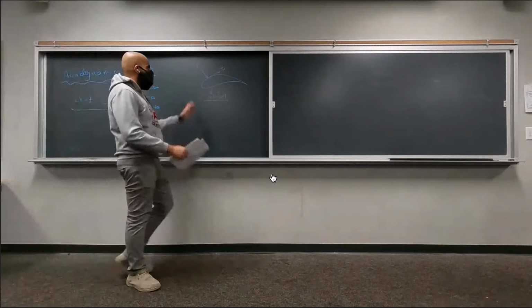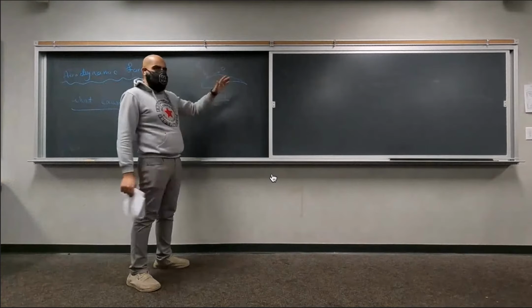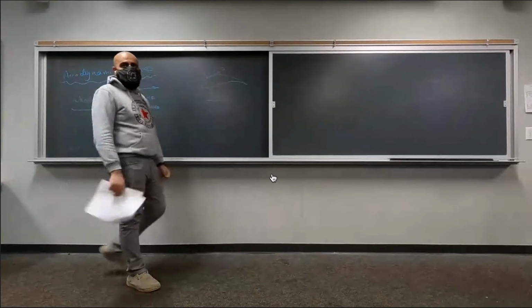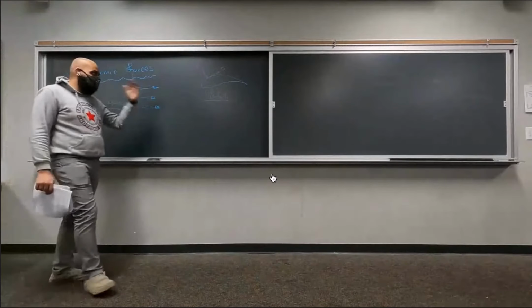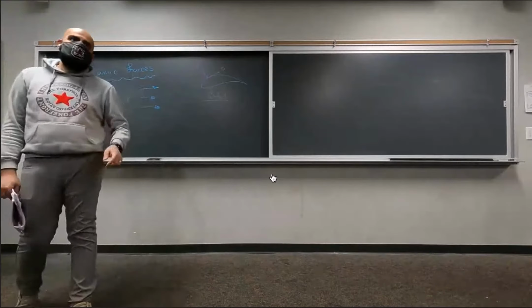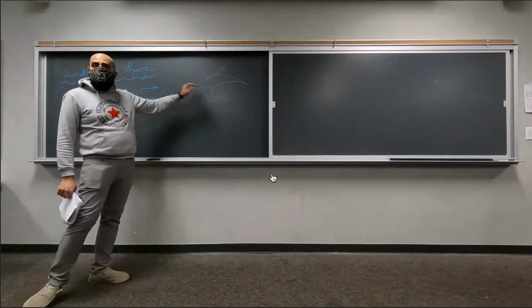So we are going to have a normal pressure distribution all over the wing, as long as it has air around it, and we are going to have a shear distribution all over the wing as well. If you take the integral of these forces, you're going to have the resultant force and moment that is being applied on this airfoil here, right?